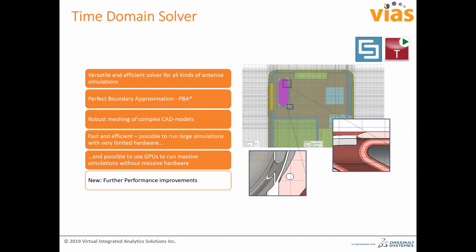It can be a case like an aircraft with an antenna installed on it, where the aircraft size is 42 meters, and in wavelength it is around a 2000 lambda structure. That is the type of structure I'm talking about. But if it is fairly small, like a 20 lambda or 50 lambda structure, you don't need to go for GPU computing. You can do it with a standalone system with around 128 GB of RAM and a CPU processor of 3.6 gigahertz or 2.7 gigahertz.